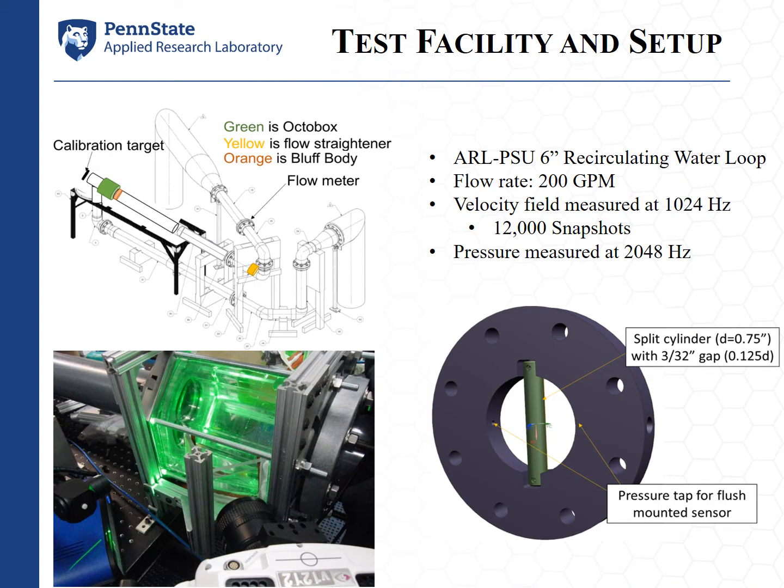Synchronously with these PIV measurements, we acquire pressure transducer data on either side of the cylinder, which is shown here in the bottom right. The cylinder is just upstream of the measurement location, and again that provides a flow disturbance that we somewhat understand. It's somewhat well understood already, and we can benchmark some of our analysis techniques on that.